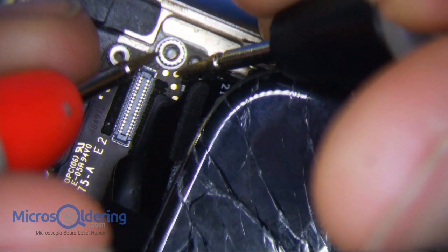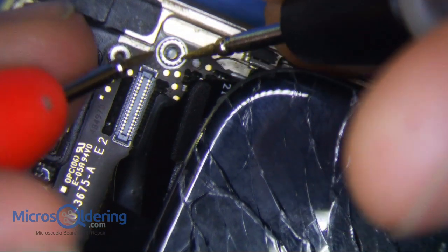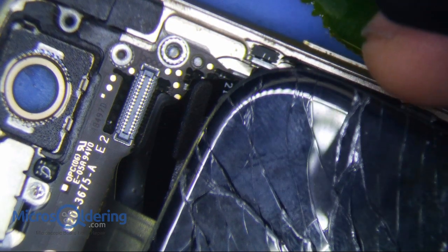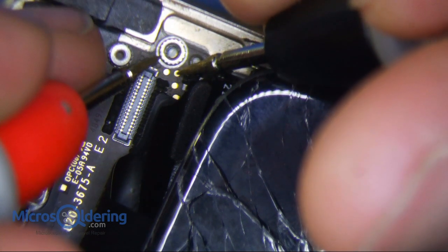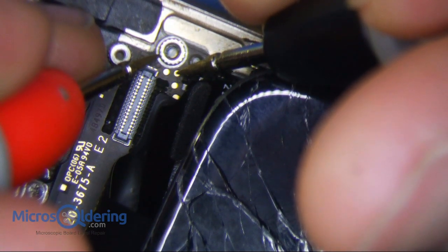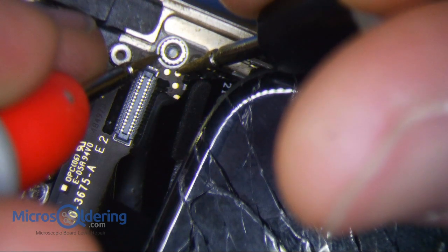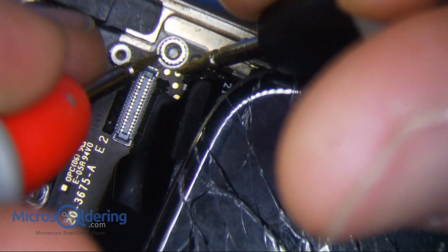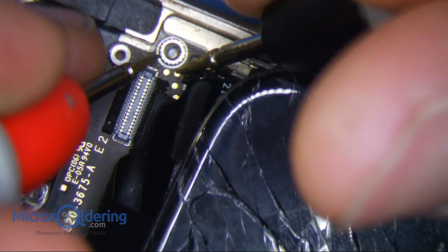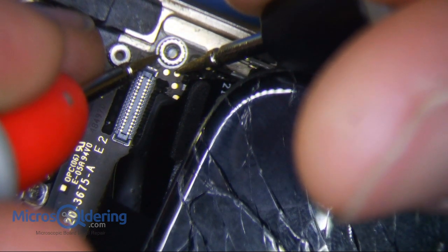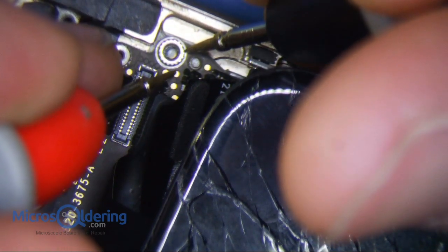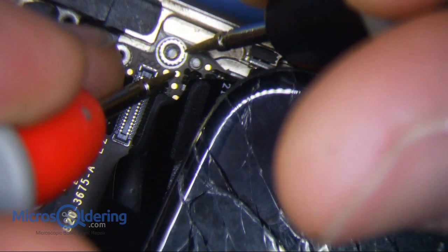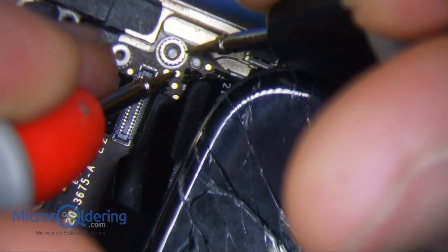So this is the bad phone. I'm just going to set the multimeter to DC voltage mode, touch one lead to ground, and the other to this point right here, which is going to give me the voltage across the anode line. Okay, so this one shows 11.4 volts. It says negative 11.4 volts, and does it really matter if my black lead is on ground or my red lead is? No, it doesn't really matter, because I can just switch it right now, and it's going to give me a positive voltage. All right, so the only thing you really care about is the actual voltage. It doesn't really matter which lead you put where, the colors and stuff like that.